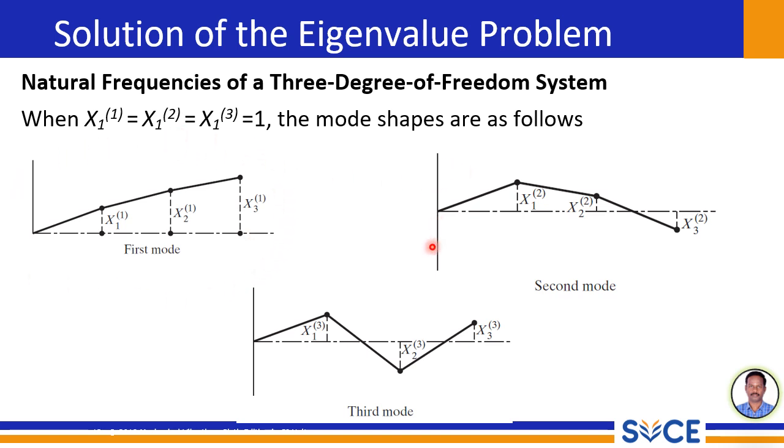The second mode occurs at the second natural frequency. In this mode, the masses vibrate with a more complex pattern. The first and second masses move in the same direction, that is the positive direction, with the second mass having a smaller amplitude, approximately 0.445 times that of the first. The third mass moves in the opposite direction with an amplitude of about 0.8 times that of the first. This mode exhibits one node, a point of zero relative displacement between the masses.